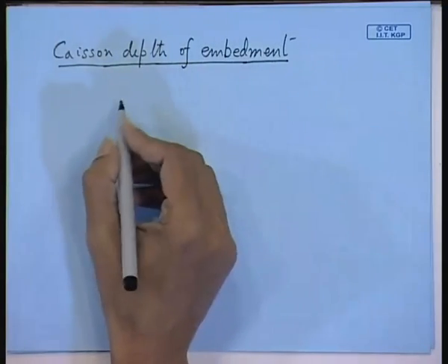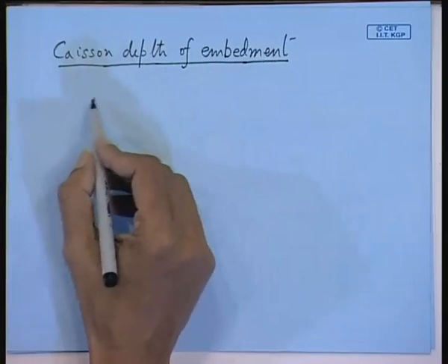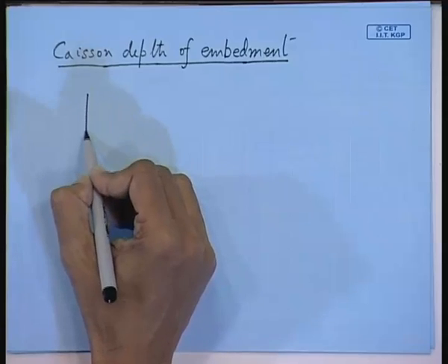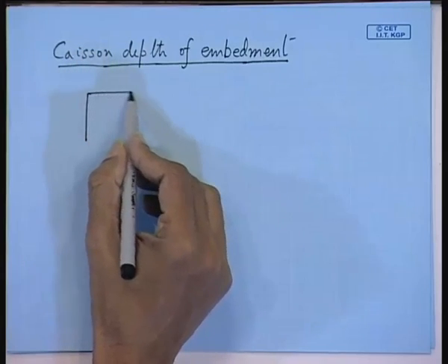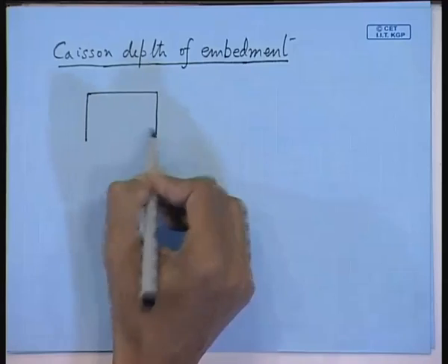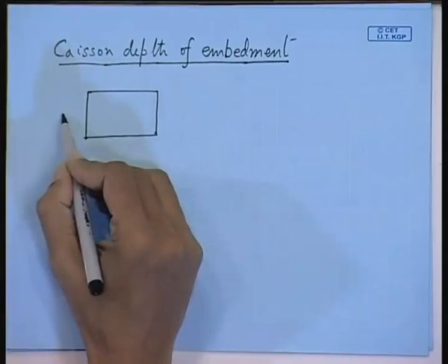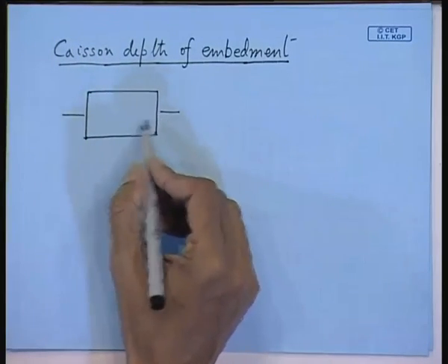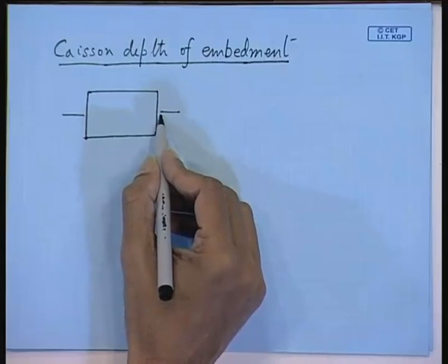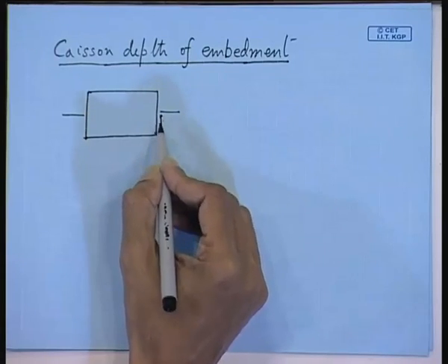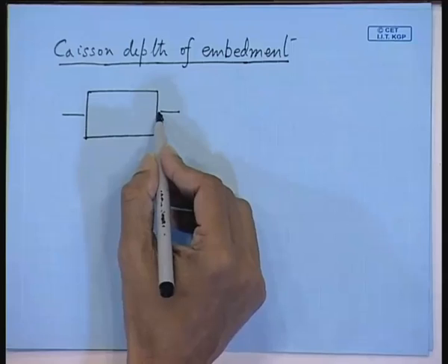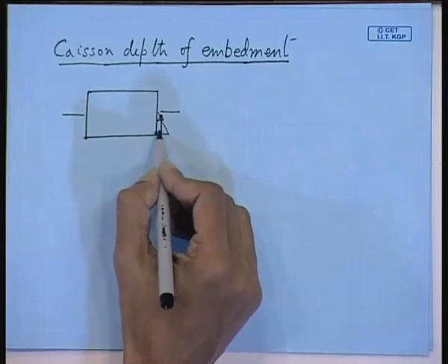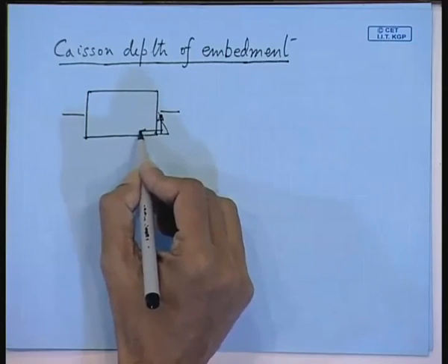So, this is calculated from the well foundation mechanics. This is your, say, Caisson and this is your seabed. You find out how much friction force is coming from the soil, and the soil will also give you a lateral pressure like this.